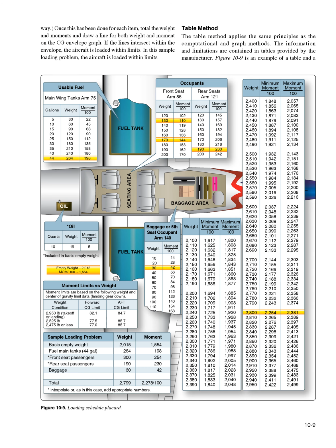Loading problem: the aircraft is loaded within limits. Table method: the table method applies the same principles as the computational and graph methods. The information and limitations are contained in tables provided by the manufacturer. Figure 10.9 is an example of a table.